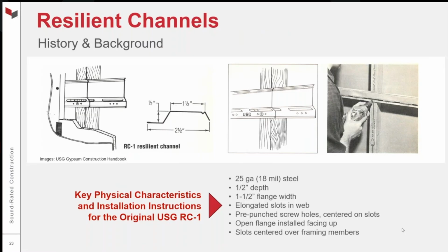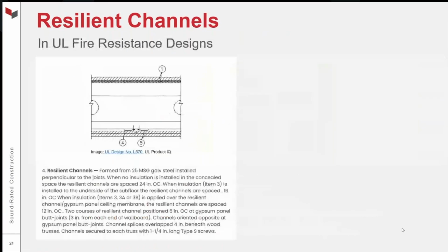And these characteristics are key because they really promoted significant improvements in STC. They were very, very effective at decoupling the gypsum panel from the framing, resulting in high STC. They also improve fire performance, especially in horizontal assemblies. So the resilient channels, again, were invented to improve sound and fire performance.